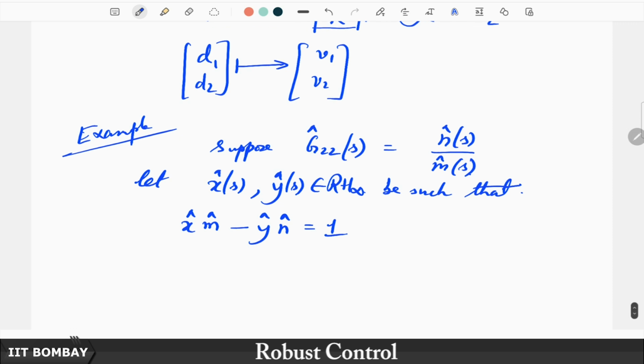So, we will always have this co-prime factorization, provided that there is nothing cancelling out, that is a given, right. So, it is co-prime. So, this n and m are co-prime, and therefore, this co-prime factorization exists. Let me just clarify and mention it. It is coming due to the Bezout identity, co-prime factorization. So, this is Bezout's identity, just to refresh your memory.